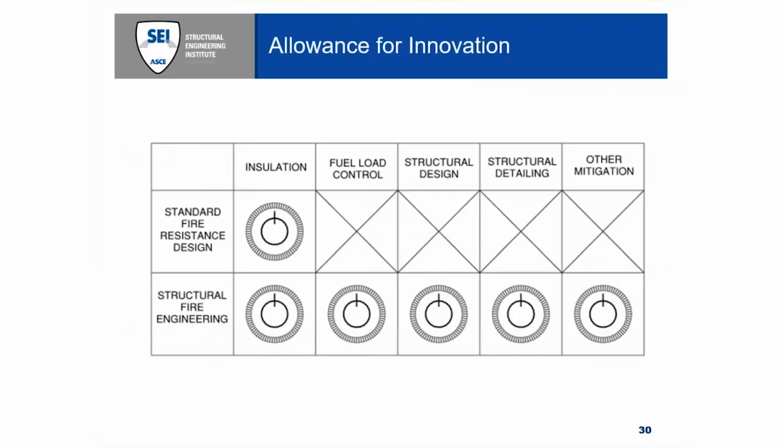With the expected proliferation of structural fire engineering in the United States comes new opportunities for us as structural engineers. I can't stress this enough. Since standard fire resistance design is fully tethered to an empirical indexing system that has remained relatively unchanged for a century, designers are only able to influence a small number of design variables, primarily the level of protective insulation that designates the structural system components based on furnace testing.